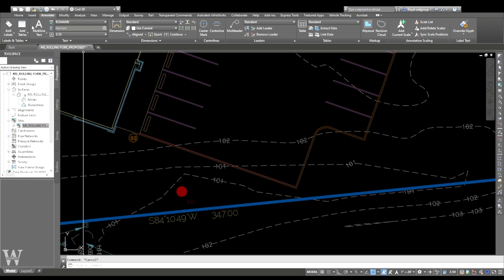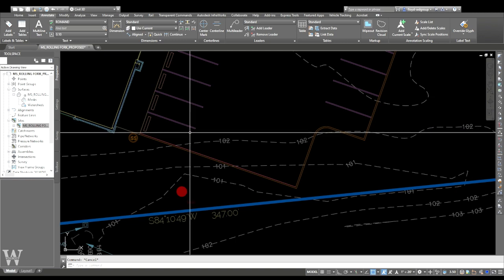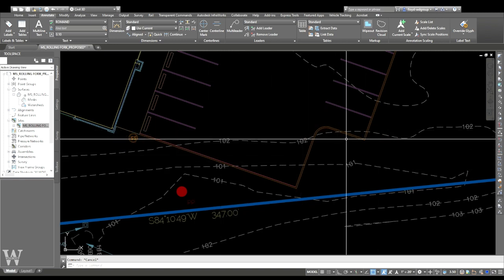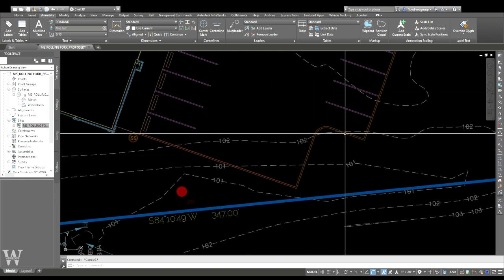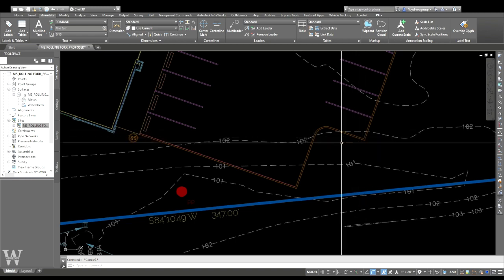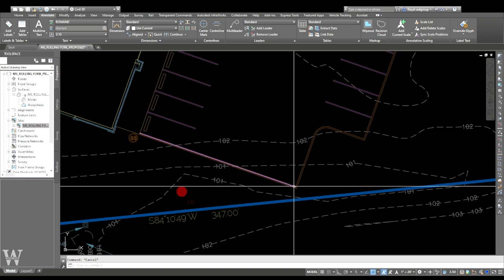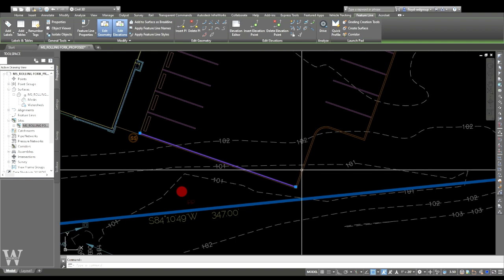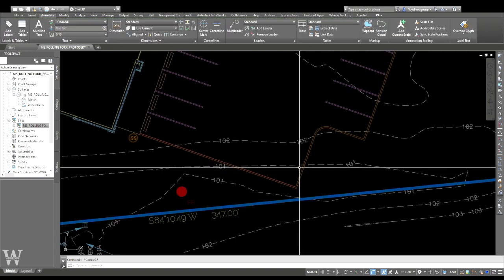I'm going to annotate, add line label. This right here is one of the best things I ever found, because when you go and start putting feature lines in AutoCAD, it's the craziest thing in the world. I can have a bunch of feature lines in here and have all the elevations. This is all XREFed in, and if I start a new feature line from the end of that feature line, half the time it'll pick the elevation of that feature line, and half the time it'll pick the elevation of that object right there, which should be on 0.